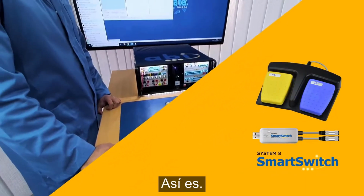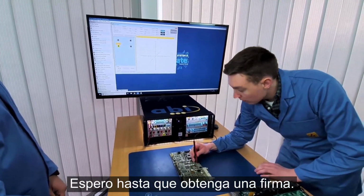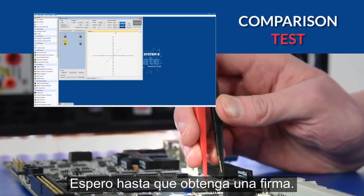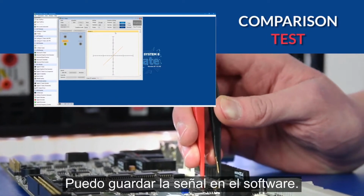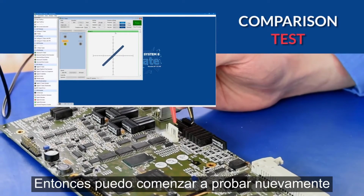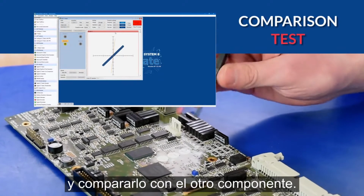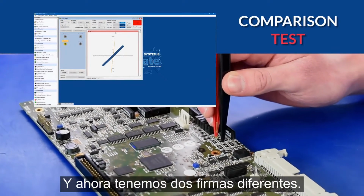That's right, yeah. So I'll start a test using the foot switch and I'll measure across that component there. Wait till I get a signature, like I have. Start the test. I can then store that in the software. There we go. And then I can start a test again and compare that against another component. Here we go. Stop that. And here we've got two different signatures.